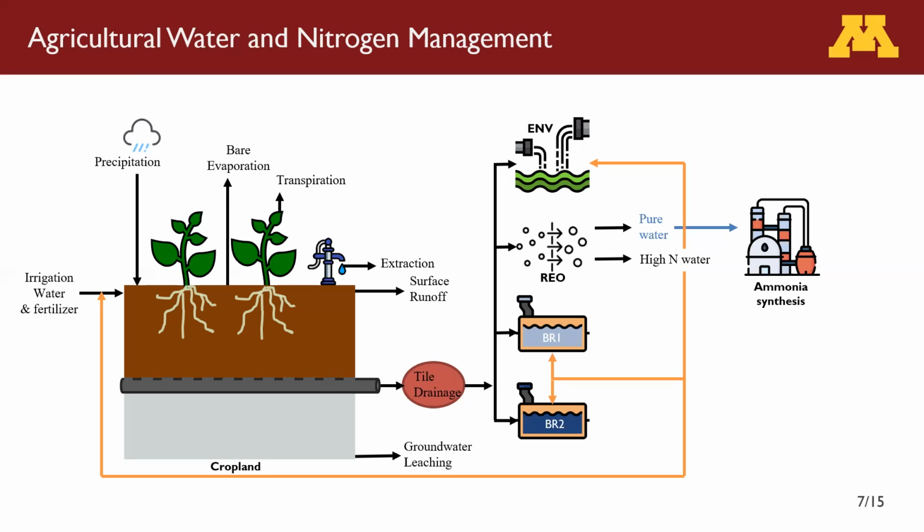The bacteria in the reactors can break down the nitrate in the water passing by through denitrification or other biochemical processes. Denitrified water leaves the bioreactor, and can be sent to the second bioreactor for further denitrification, or sent to the reverse osmosis for purification. Here, all the nitrogen-containing water which does not go to the water treatment process or cropland is deposited into the environment, considered deposited wastewater, and referred to as nitrogen loss.